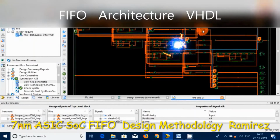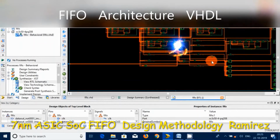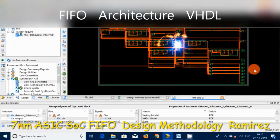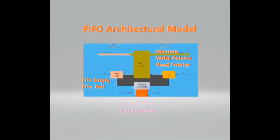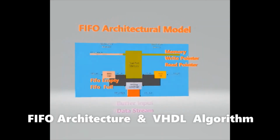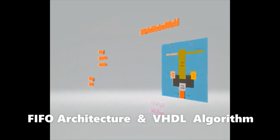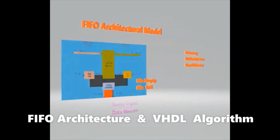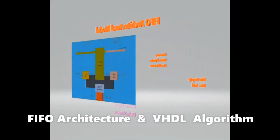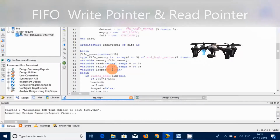The FIFO is used to buffer the minimum number of burst data in order to guarantee continuous reading from the FIFO without interruption. So in this case, the FIFO read control logic block checks for the almost empty flag going high and sets the FIFO read control signals to read continuously from the FIFO.